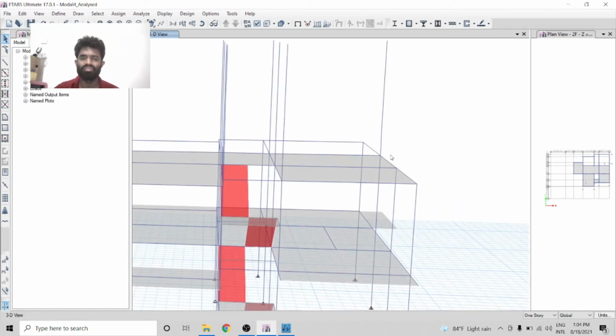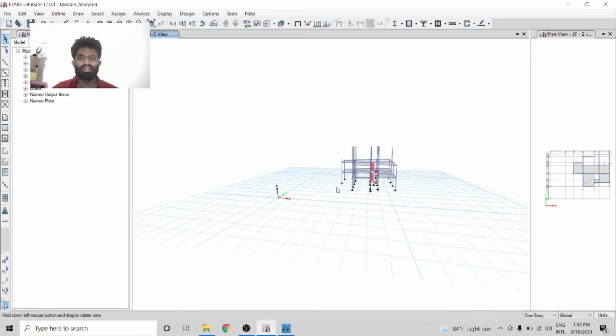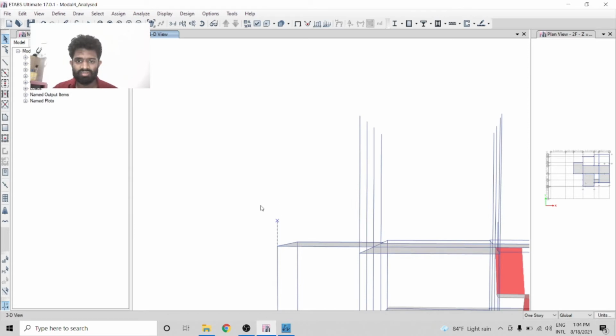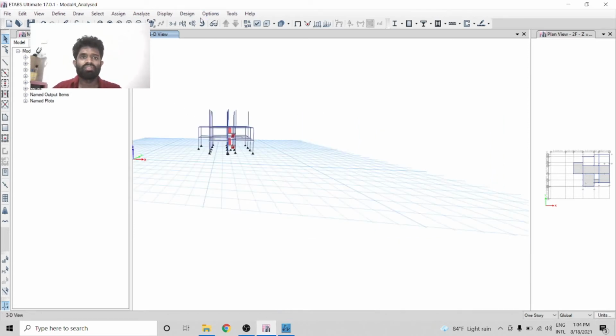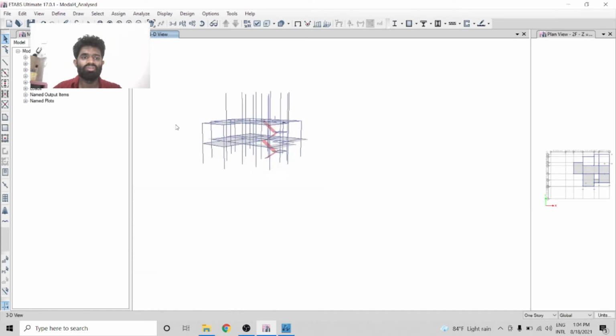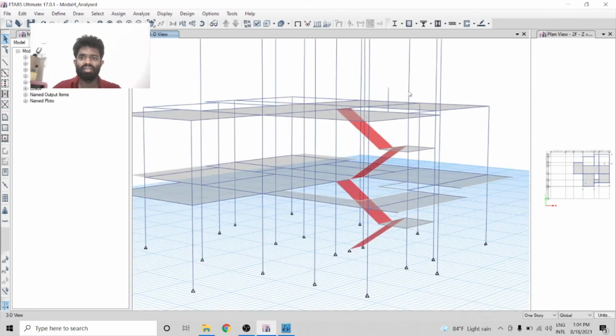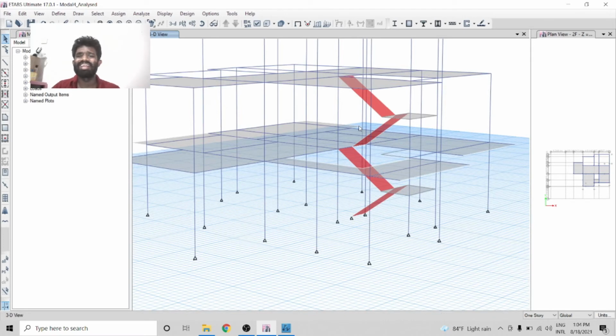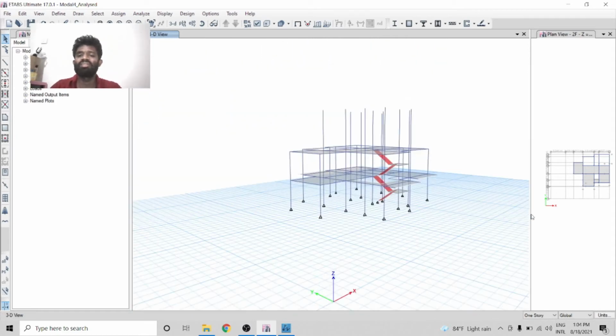These two columns can be drawn. Now the roof load can be applied to these columns. So our 3D model is drawn and that is finished. We can now apply the loads and do the modifications to the load bearing things and the supports, and the drops can be released for the moments, and those things can be discussed in the next part.